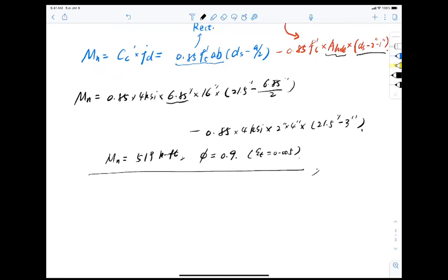I utilize the superposition. Why? I can use the superposition because the compressive zone covers the opening. So when I say this, it is to say that this irregular section is the simplest irregular section you will ever see. Nice opening in the compressive zone, take it out, done. Is that right? But in reality, it doesn't go like that.